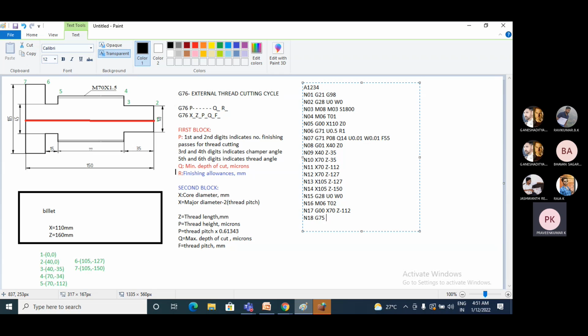So now I'll use retract. I will follow the syntax, retract of grooving. So it is R1. See, after making the groove, the tool has to retract 1 mm above. So next I'll go to N19. Go to the next block N19. So again it is G75,